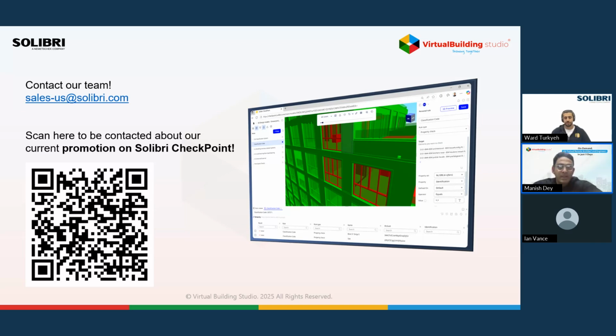Does Solibri provide a CSV template? We don't actually provide a CSV template for Solibri Checkpoint. However, any CSV file can work, basically. You don't need to actually import the whole file into Checkpoint. All you have to do is copy it as a table from Excel in CSV format, or even have it in a note and so on, and then drop it into the filter editor. And Checkpoint will understand it's a CSV table because of the CSV format, basically.